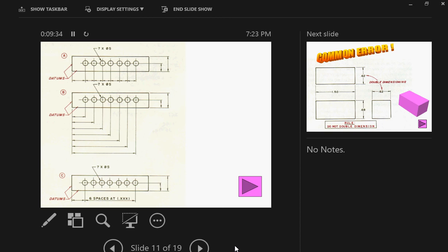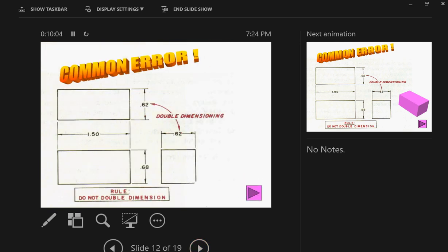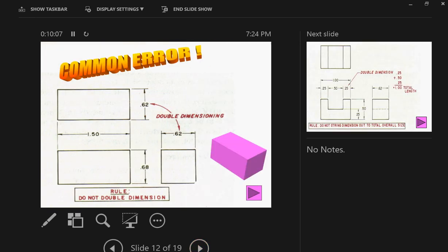Okay? Over there on the top one, you've got what's called stack up. Because if the first hole's off by 0.05 and then the second hole's off by 0.05 and the third hole's off by 0.05, what happens to that last 9th hole? It's way out in Pluto, right? In terms of lining it up with whatever it's supposed to line up to. So while A is correct, if you've got a stack-up issue with tolerancing, it could create issues.